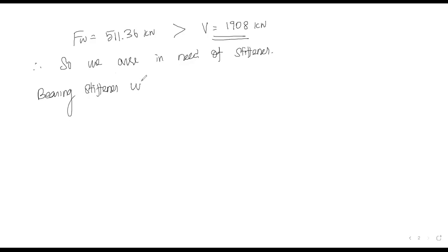Bearing stiffener will be designed for the value of the balance force, that is V minus Fw.